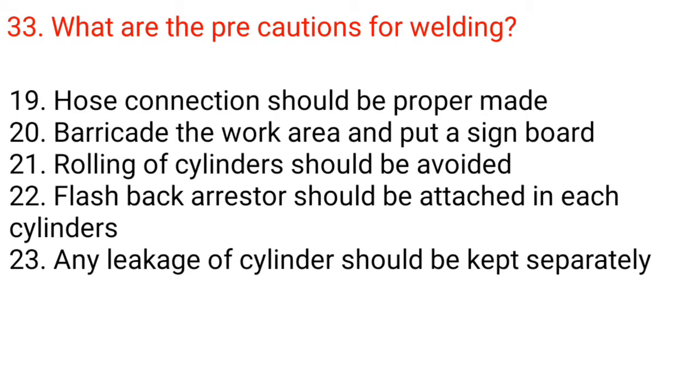19. Hose connection should be properly made. 20. Barricade the work area and put a signboard. 21. Rolling of cylinders should be avoided. 22. Flashback arrestor should be attached to each cylinder. 23. Any leaking cylinder should be kept separately.